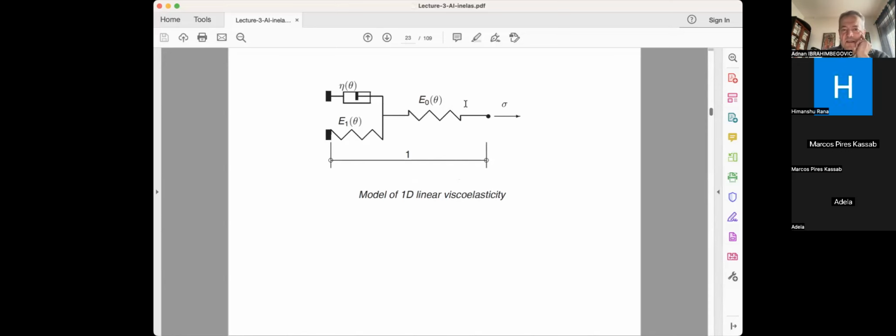So you can see here that at any section I decide to cut this, there will only be one stress component going from the free end, where I apply this stress component, to the built-in end. In order to keep equilibrium, sigma is constant at any value of x that goes from 0 to 1. And then if I stretch it, of course, I'll have my epsilon, a deformation.